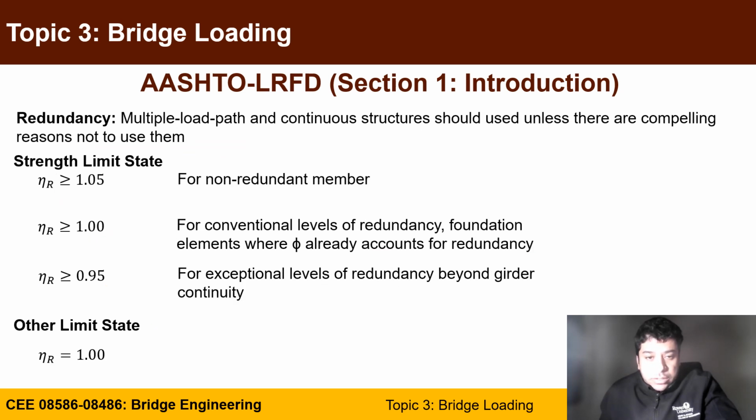For redundancy, if your structure has only one load path and this load path is interrupted by any failure, that means the entire structure will fail. If you have more redundancy in your system, it's always positive. So the definition of redundancy is multiple load paths and continuous structure should be used unless there is a compelling reason not to.